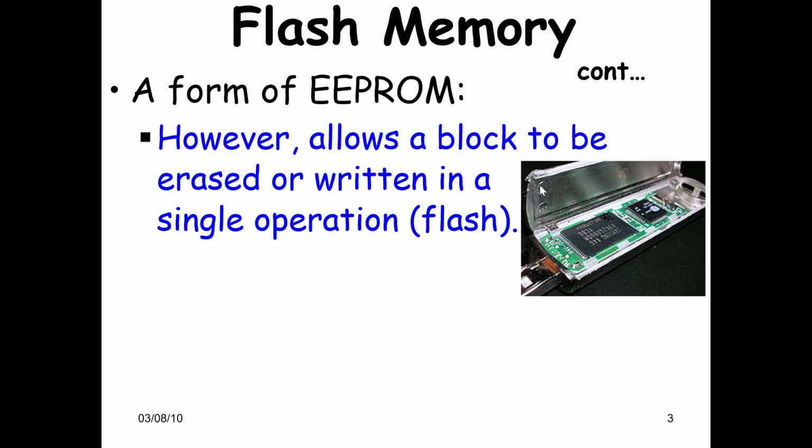So flash memory is basically a persistent memory in the sense that if we turn off the power, the data disappears in a DRAM, right? But in the case of a flash memory, if we turn off the power, then the data still remains. All right, so this is why it is known as a persistent memory. So in the older days, we used to call it also an EEPROM, in the sense electrically erasable and programmable read-only memory. But again, if it's programmable, it's not read-only, right? But you need to give this much of a leeway to history.